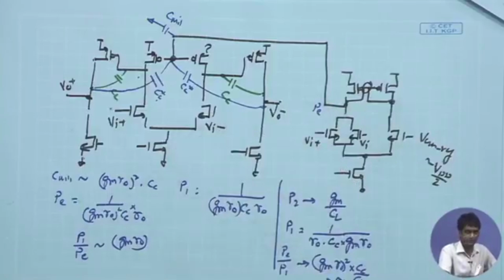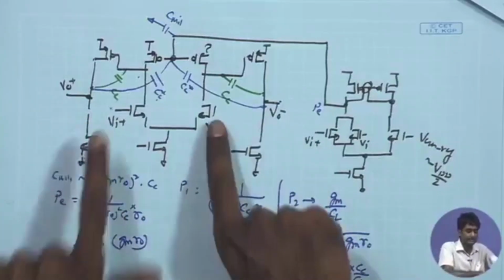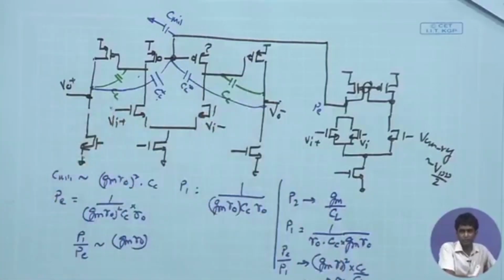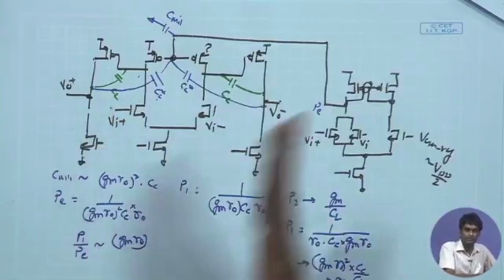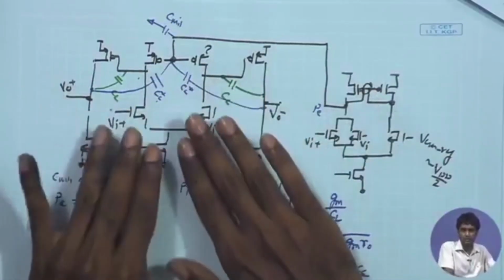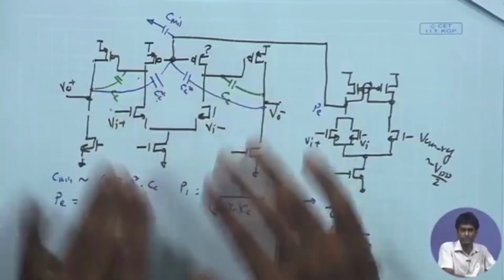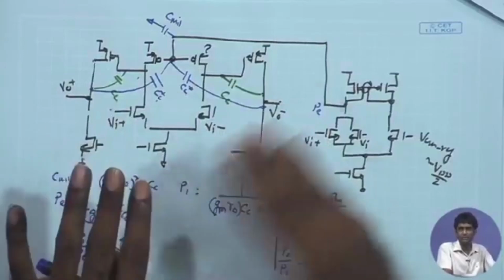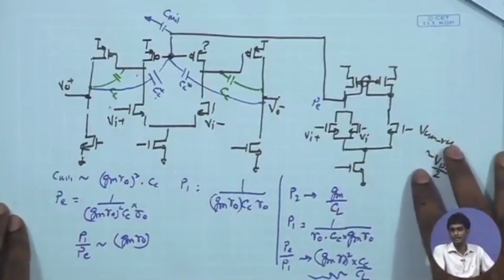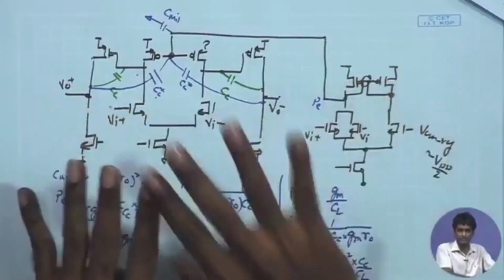So, another exercise on noise analysis also has been suggested, where you have to size the transistor appropriately, so that the 1/f noise corner is pushed towards lower frequency, and then you have to make sure that the bandwidth of the differential amplifier for the differential operation along with the CC compensation is sufficiently higher than the 1/f corner frequency. So, that is another interesting example you can look at. So, just designing this front end amplifier has so many trade offs.